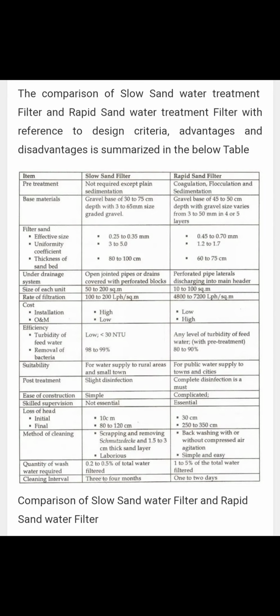Aeration has various types that we already discussed. After that, we discussed sedimentation. Sedimentation is of two types, plain sedimentation and sedimentation with coagulation. These are also called type 1 sedimentation and type 2 sedimentation. Type 1 sedimentation is nothing but sedimentation without a chemical, without coagulant.